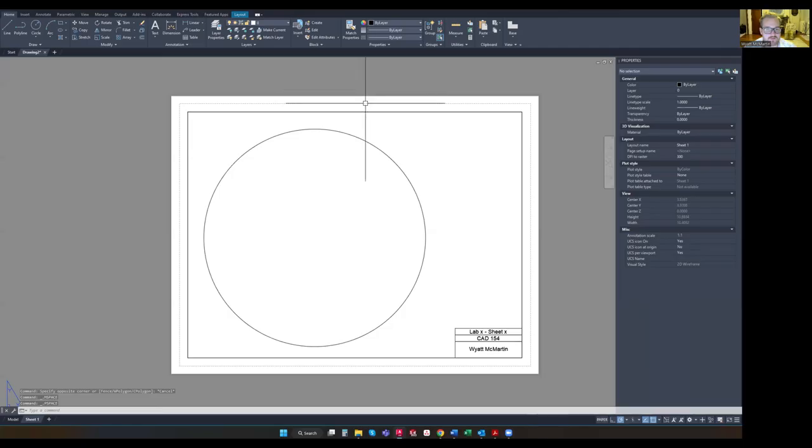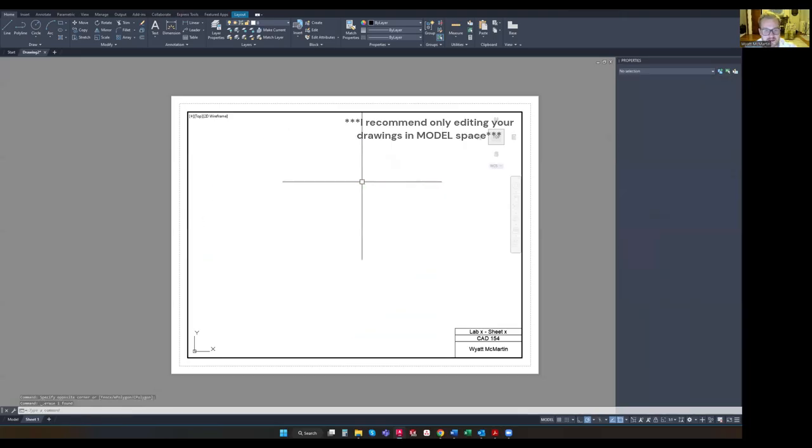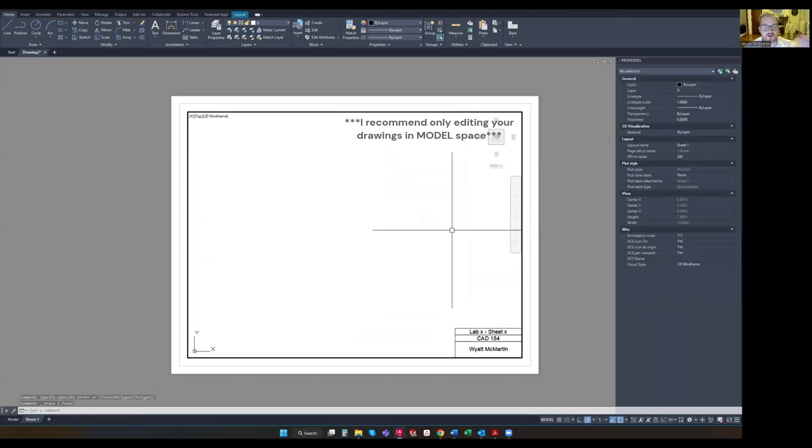And if we want to delete something from here, you can't. You can't highlight it from here. You have to double click in, then you can highlight and delete. So what we're going to do now is we are inside the viewport. We're still at 1:1. Everything's positioned the way we want. We're going to click this lock button.